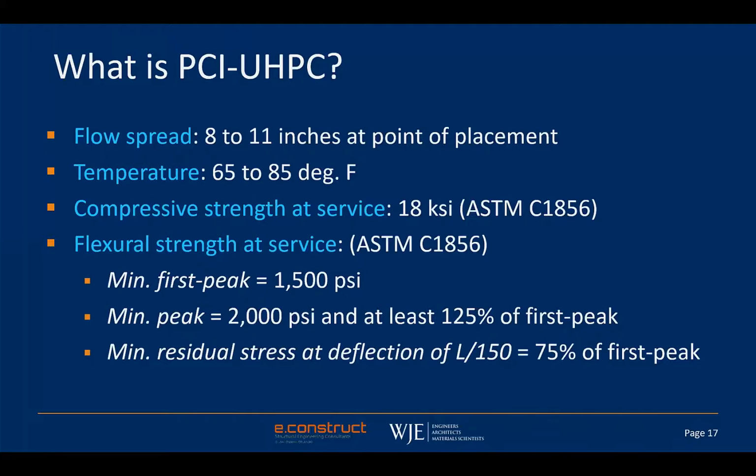We're targeting a compressive strength of 18 KSI. And while compressive strength is relatively easy to test and familiar to most of us, we are de-emphasizing the importance of compressive strength in favor of the flexural strength. Flexural strength is the most important parameter since that's what really adds to the capability of the precast UHPC compared to what we're used to.